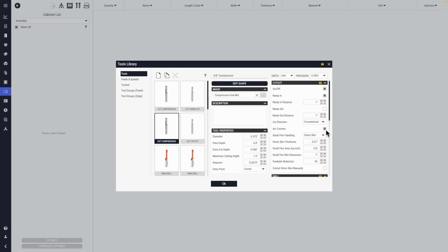If you are noticing that your outside corners are getting some bumps or some extra cuts out of it, it usually has to do with some precision setting within your CNC, but you may also try turning it off and then checking the results. Small parts. Small parts are going to have trouble staying still while they're being fully cut out from the material, because the pull of the vacuum, if you're operating with a vacuum table, the pull is directly proportional to the area of the small part.